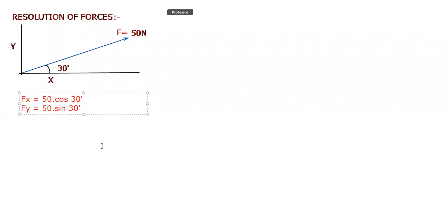Now you all know the sine, cos and tan, right? So you can calculate these values by using your calculator. Okay, so this is called the resolution of forces. If n number of forces are there, then you can resolve those forces, and the resultant of those forces can also be found out by using the resolution. So you can find the resultant by the resolution.